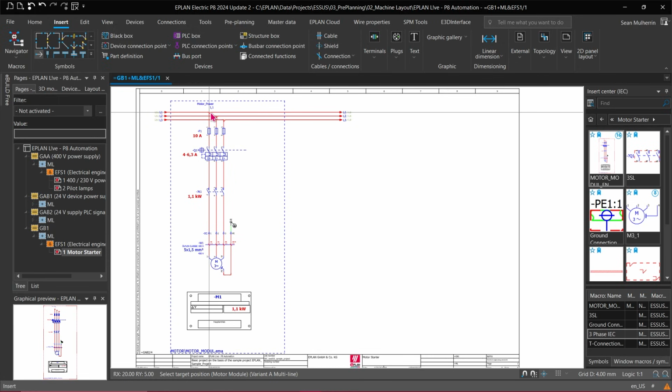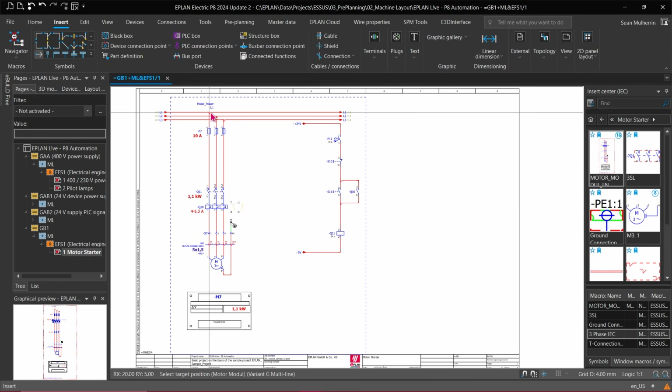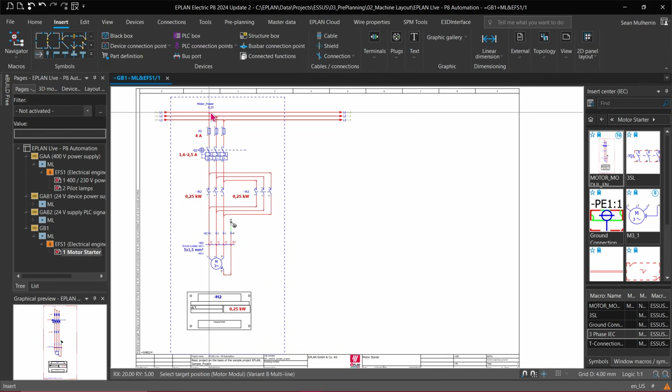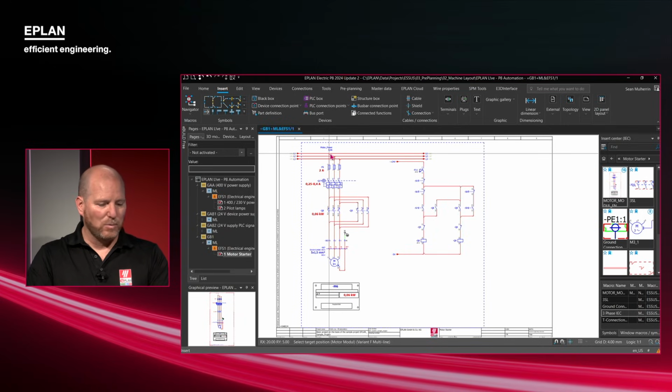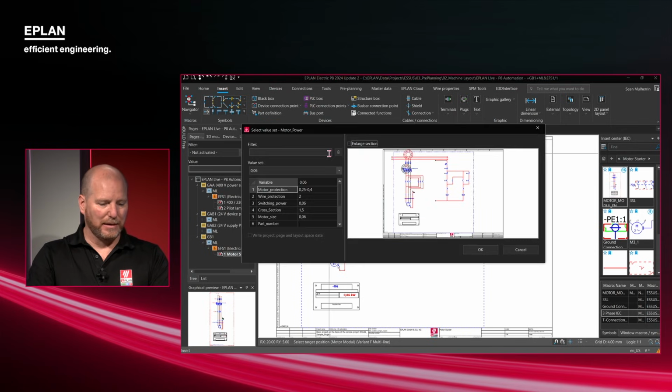user. And now using the tab key, you can see I can access different variants. So these are the variants of that particular circuit. So simply using the tab key, I can access all 26 of the variants. I don't have to create 26, but if I do, I just use the tab key to access them. And then once I've selected the tab key, I just simply place it, and now we're talking about the value